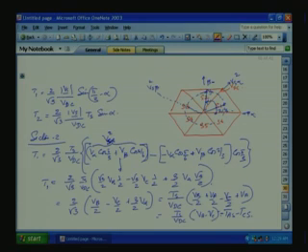Why fictitious? Because the Va, Vb, Vc amplitudes, as it moves to different sectors, can go both positive and negative. So, TAS, TCS can also go positive and negative. What we want is only positive time to find out the switching instants. We will come to that now. From our T1, T2 equation, using the sampled reference phase amplitude, we are converting to a fictitious time. That time is proportional to the sampled reference phase amplitude multiplied by our fixed sampling period divided by VDC. So, TAS, TCS. In a similar way, we can substitute for T2 also.